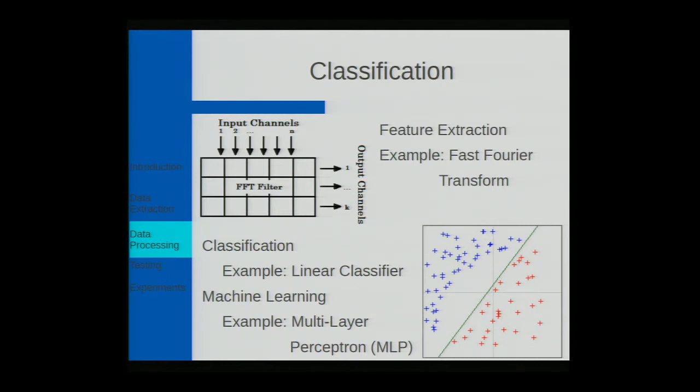If the user's moving, that's louder than the brain is, because the muscles along the head, if I smile, these things go crazy. So it's actually probably easier to use a headset with someone who can't move, because you wouldn't have all of those additional artifacts. But there's a lot of filtering that has to go on. In general, common average reference works because it adds over everything and subtracts the common average from everything. Not always. We can add in a couple different classifiers if we want.